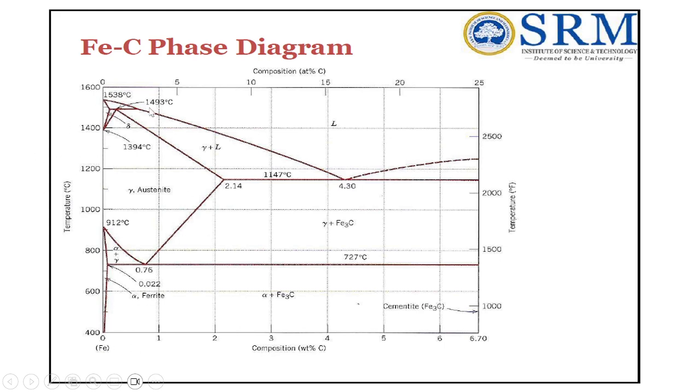This is what you have to understand from this iron carbon equilibrium diagram. In addition, you have to note down three different phase transformations that take place: the peritectic reaction, the eutectoid reaction, and the eutectic transformation. At the top, the peritectic reaction takes place. At the bottom on the left hand side, you can see a eutectoid phase transformation, because already one solid is formed. So this becomes eutectoid now.